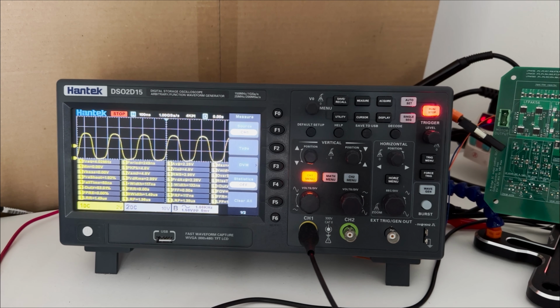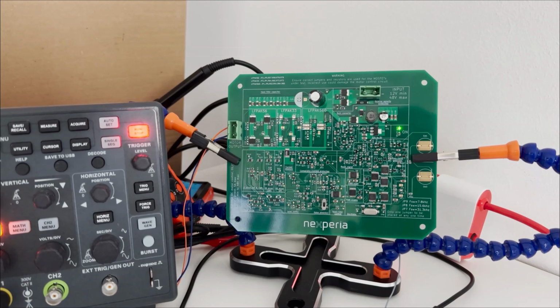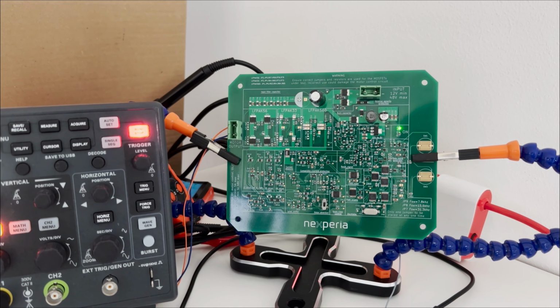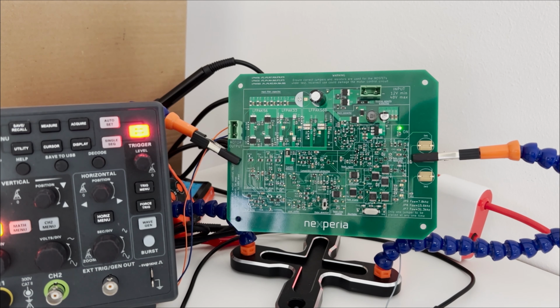If you look at the signal, it is the 4 MHz crystal oscillator output. The waveform is in sinusoidal form. But there is a possibility that the circuit I'm using doesn't require this high frequency. I want a proper square wave which can be fed to some circuit like gate drivers. For that, I have to use some different type of circuitry.